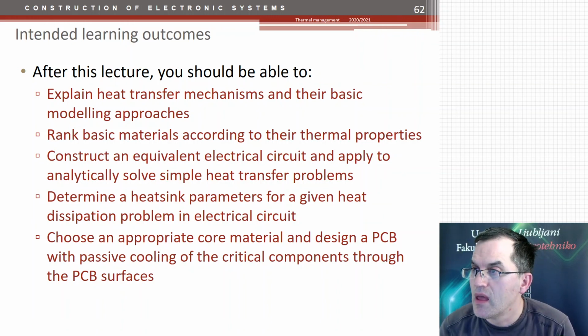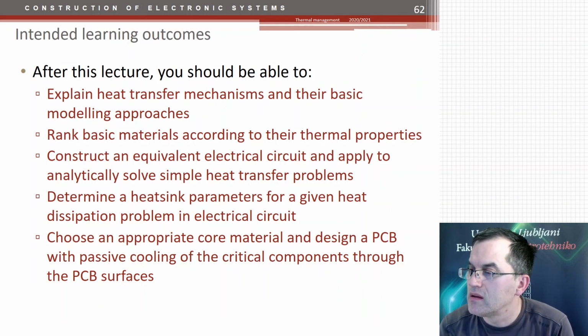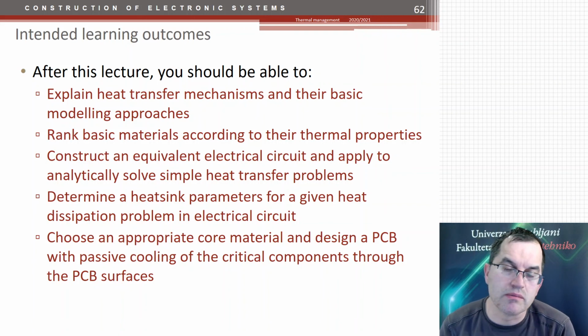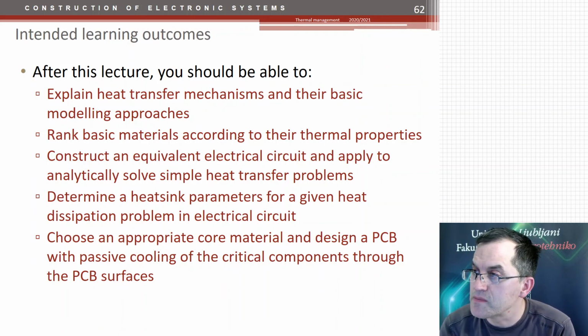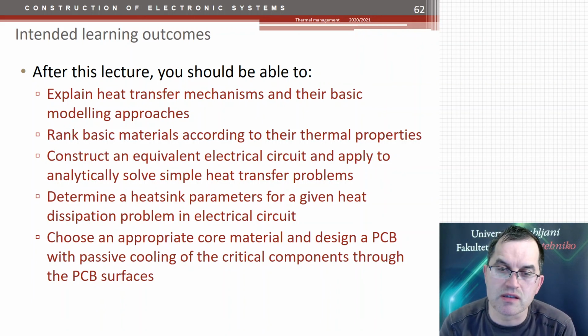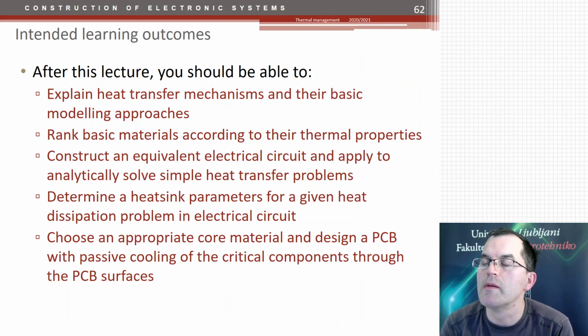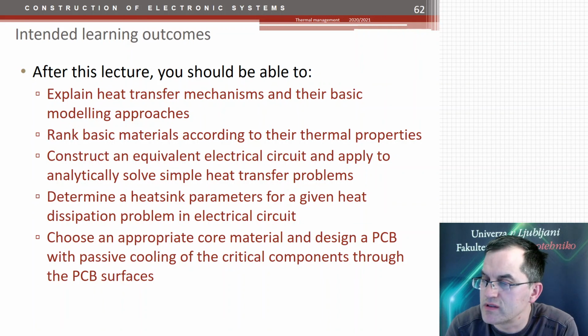Then you should be able to construct an equivalent circuit for a simple thermal, or cooling, task. So you should be able to construct an equivalent electrical circuit with electrical resistances that would then be used for simulating the heat transfer, and then calculate a simple heat transfer problem.